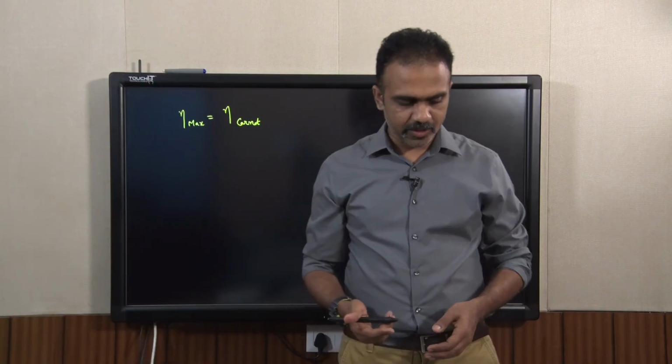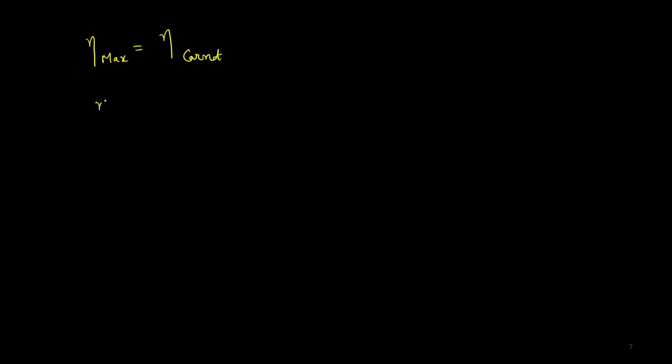There are other corollaries to it. We can also show that the efficiency of the Carnot engine is independent of the working fluid. So you can have any working fluid inside, it doesn't matter, the Carnot engine is always going to have the same efficiency, right? That again can be derived from the fact that you can combine an engine and refrigerator working with two different fluids, and if they have different efficiencies, then it will violate the second law, right?